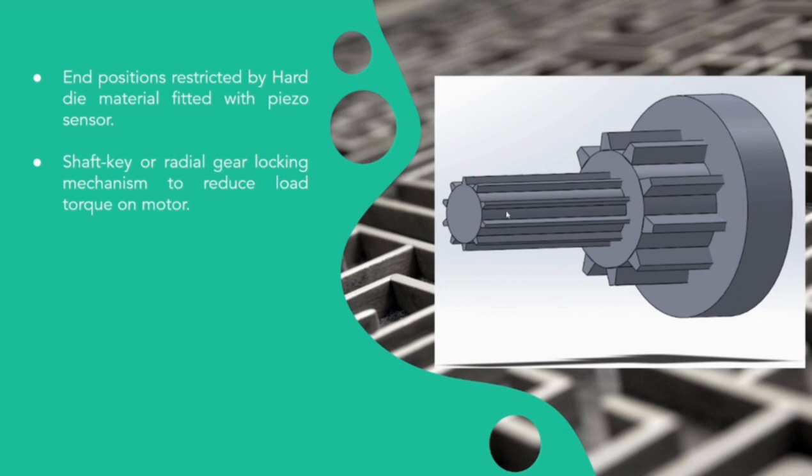Here, the innermost shaft is the shaft of the staircase. The middle one is the motor torque-producing part, and the outer is the lock. So what happens is, when the folding of the staircase is done, the lock is first attached to the shaft, and the motor is detached. So the lock holds the staircase shaft until all the passengers are boarded and the signal comes to fold it back. Once the signal comes, the lock will detach and the motor is again attached to the staircase. So it will also let it fold to its original position.